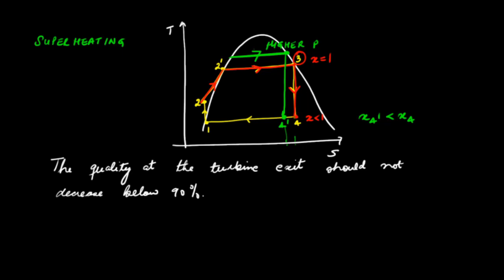So what is done in superheating is that all these processes are the same. So compared with the basic Rankine cycle, these processes remain the same, but now in the boiler the substance is heated so that it is not at this saturated vapor state at state 3, but it is superheated. And this is a new state. So note that this is again heat addition at constant pressure, and this is how an isobar looks like. But state 3 prime now has higher temperature than this saturation temperature.